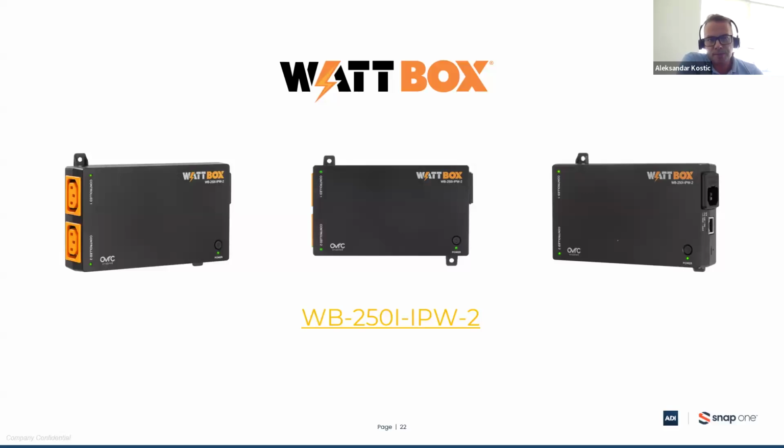The smallest one, the WattBox with 2 power outlets, has a slightly lower power budget available because the maximum current available per input and output port is 6 amperes. So if we are using, for example, 220 volts on the main network, we have around 1320 watts of power budget together on both power outlets used from this model.